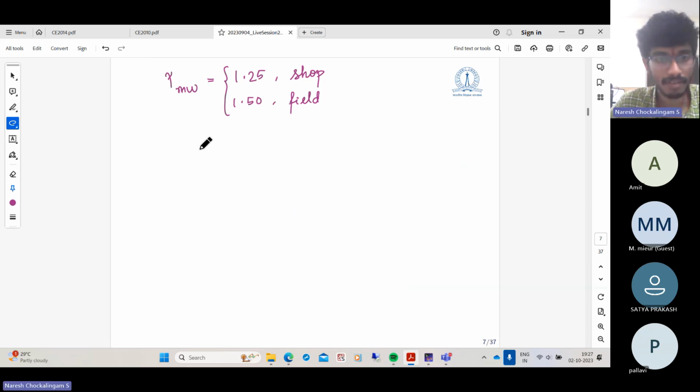The strength of the weld is given as follows. The weld is likely to fail in shear. If FU is the ultimate tensile strength of either the weld material or the parent material, typically the weld material is much stronger than the parent material. So FU is always taken as the lower one of the two because it's an interface.